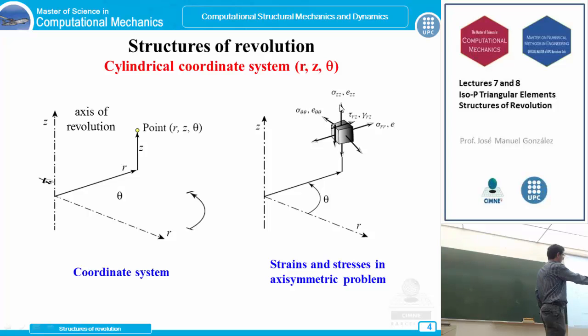We have this vertical or axial component for the stresses and for the strains. We have this circumferential component for the stresses and for the strains. We call it sigma or epsilon sub theta. And for distortions, we are going to consider this distortion rz and this distortion zr, which are in equilibrium in this common side, and the distortions in this direction, the distortions r theta and z theta, they must vanish to keep this axisymmetric distribution.